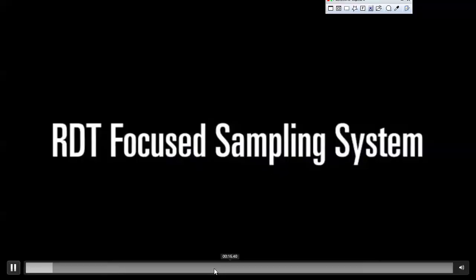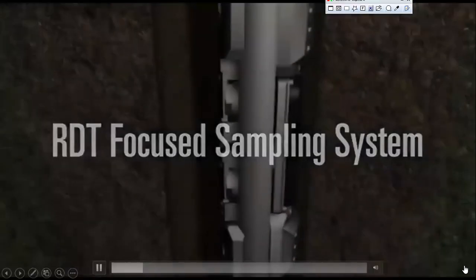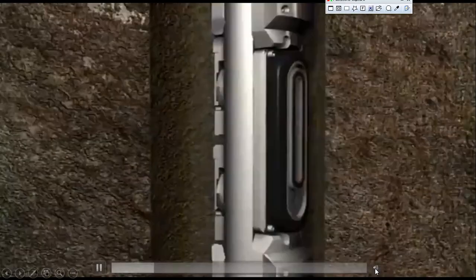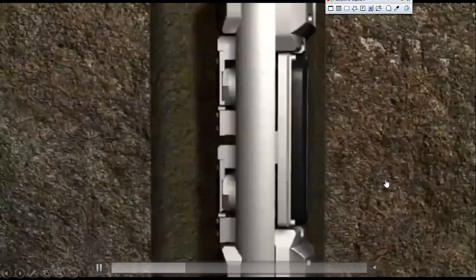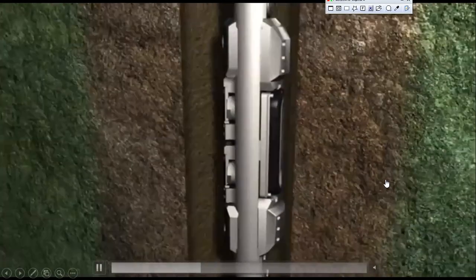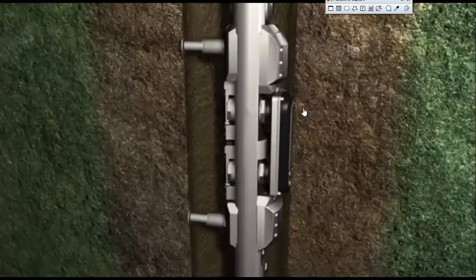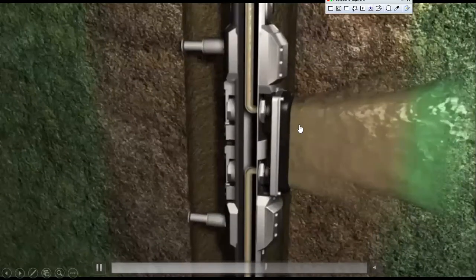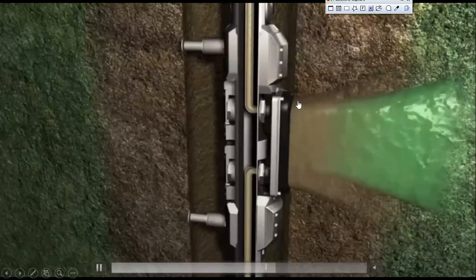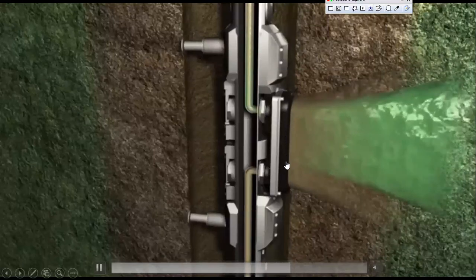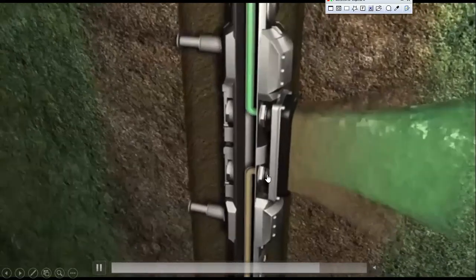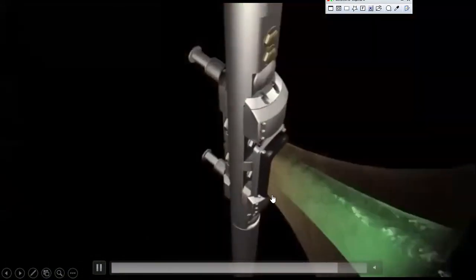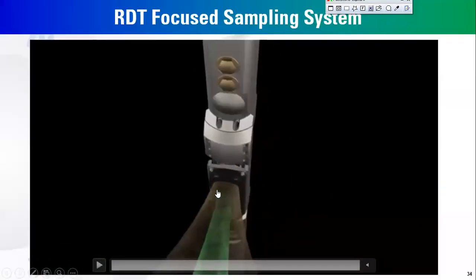So, applications. Applications of high or large flow area bottom hole sampling tools, like this oval shape probe: the flow area available for the fluid is high, so we can collect samples faster, and we can measure pressure for low permeability reservoirs, and also we can collect samples for very heavy oil systems.